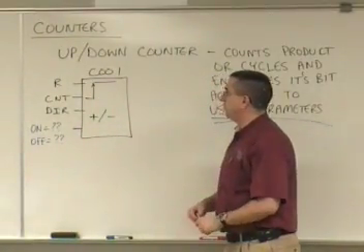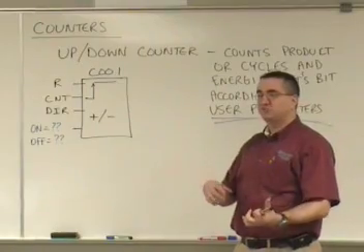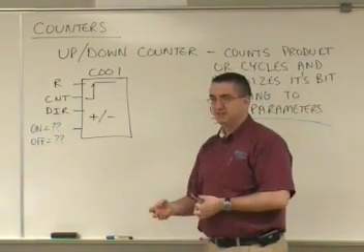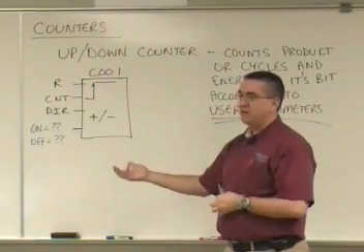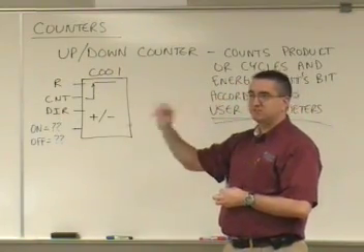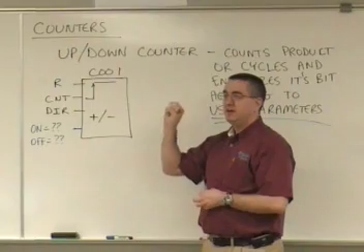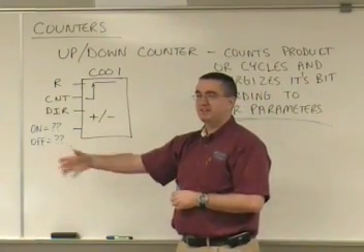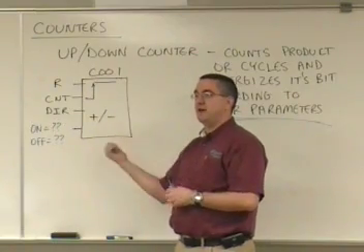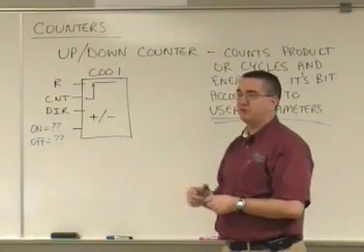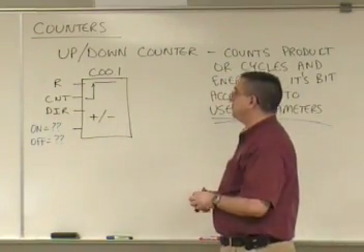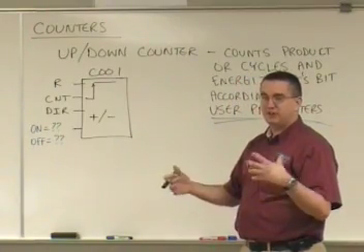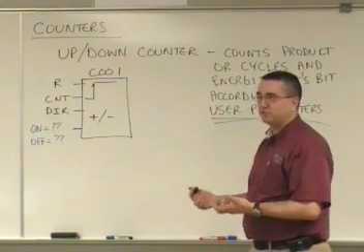As you'll discover in the future, you could also count timing bits. So I could have feeding the counter an asynchronous pulse. Remember we did the asynchronous pulse timer. And I could have one timer that counts 5 one-pulse-per-second cycles, and maybe that would turn on my buzzer or turn something off, whatever it could be. So lots of different things that you can use these counters with. Definitely designed to be utilized in conjunction with your timers though.